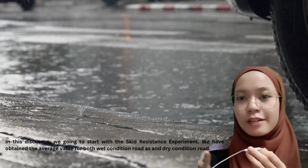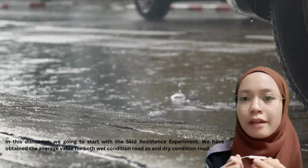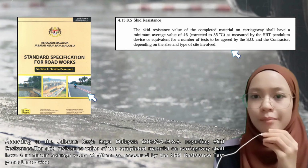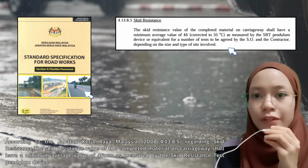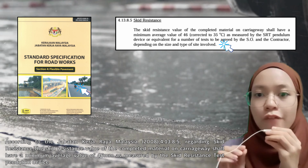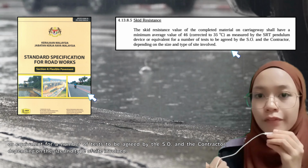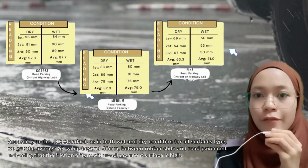The discussion will start with the skid resistance experiment. We have obtained the average value for both wet and dry conditions of the road according to Jabatan Kerja Raya Malaysia 2008 regarding skid resistance. The skid resistance of the completed material shall have a minimum average value of 46, as measured by the skid resistance pendulum device or equivalent, for a number of tests to be decided by the SO and the contractor, depending on the size and type of the site involved.